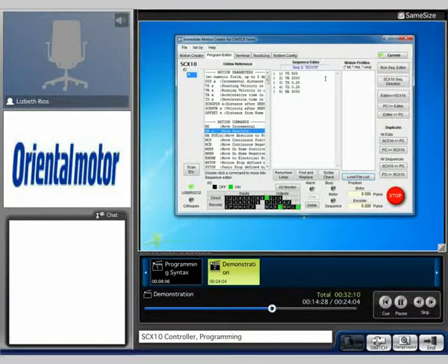And here we have the example program which we've created. We can edit this program and we can do incremental motions. So we'll delete absolute, which is represented by MA, and select distance for incremental distance value, and we want to do an incremental distance of 250.